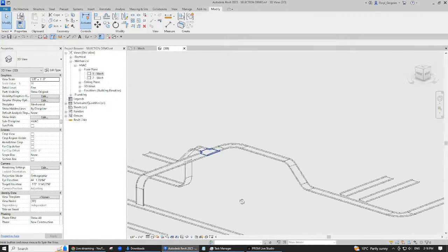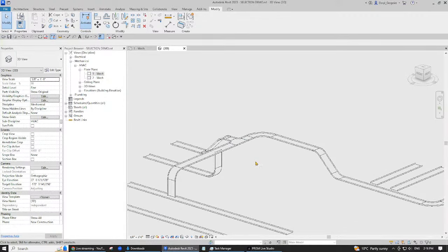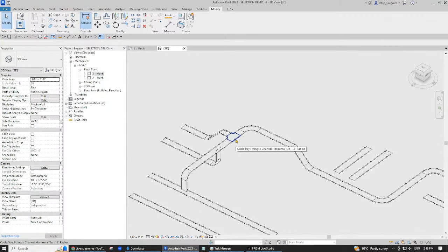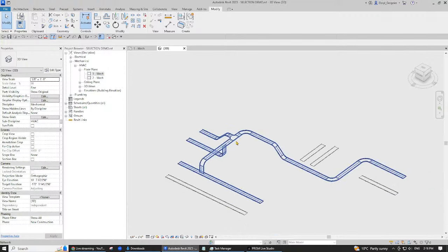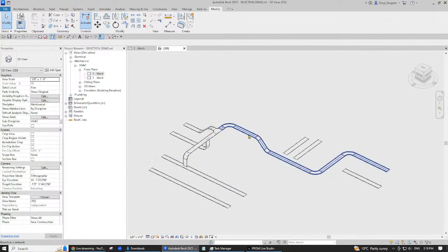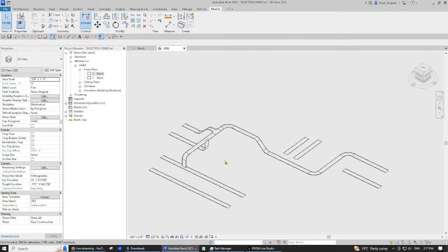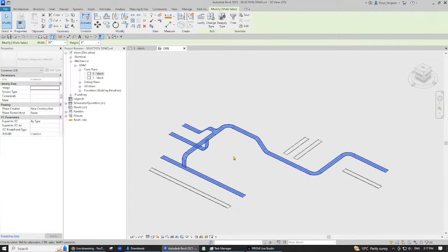Okay. Next thing is that you can just hover and tab. So hover, tab, tab. You see, that'll tell me that's all connected. Hover, tab, tab, tab, click. Now it's selected. Now I can move it or do whatever I want with it. So you can hover tab, and that'll chain select through. Then you can use your control and your shift to remove and add, and then click out.